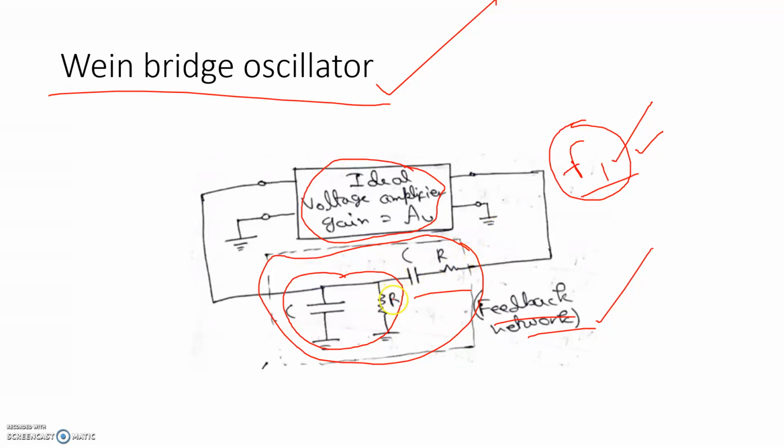So basically as the resistance changes due to change in temperature between Delhi and Kashmir, obviously the generated frequency will be different in different places where temperature difference is there, and that will affect the circuit. You have designed your circuit in such a way, so why would you have to design your circuit differently in different places? You want to make one generalized circuit which will produce F1 frequency all over the world or universe, right? So basically this you will not achieve by the Wein bridge or three-phase RC phase shift oscillator, because the resistance is dependent on the temperature.